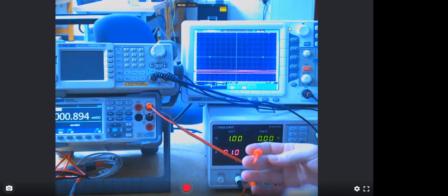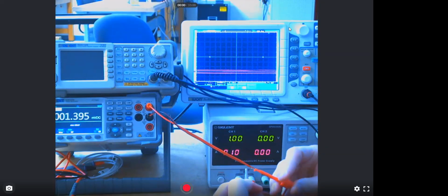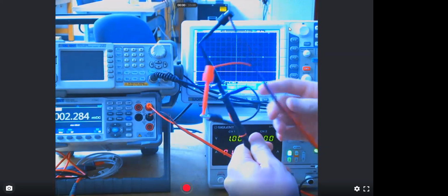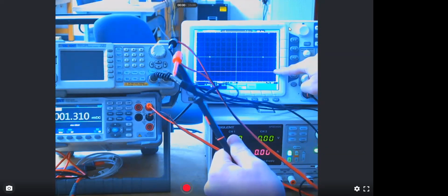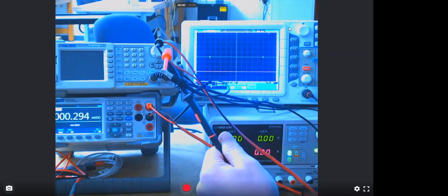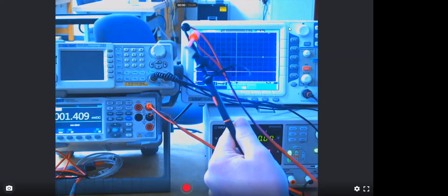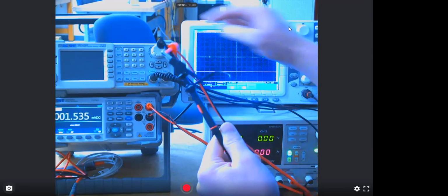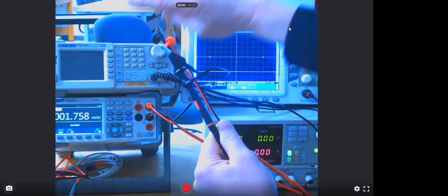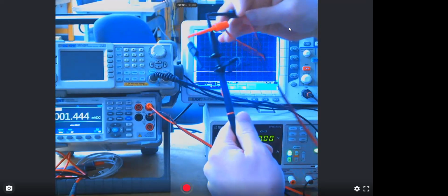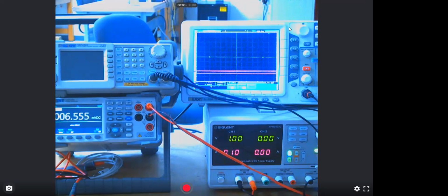And I'm applying a positive voltage to the ground or to the common reference. If I just switch the polarity, I turn this on, I should see it go down. Okay, so it's important to know what your polarity is. And that's just for DC voltage. In the second part of this lab, we're going to apply an AC sine wave to it using our function generator. So we're going to start to create alternating voltages and look at them on the scope. Let's do that now.